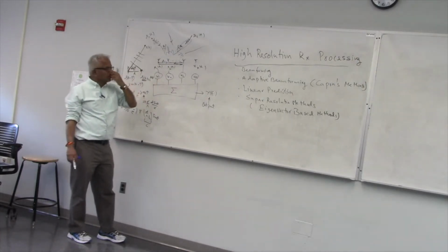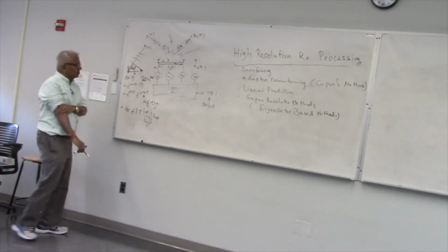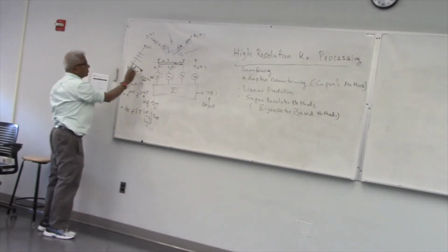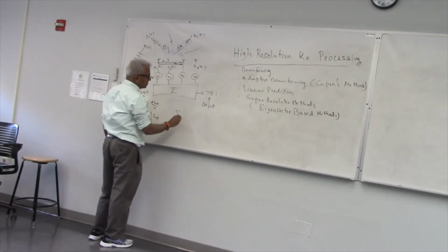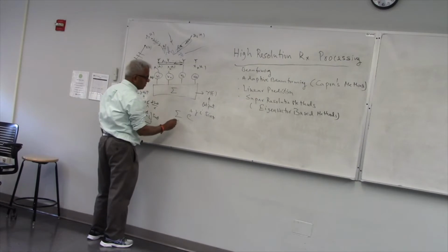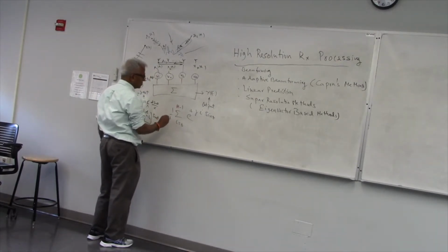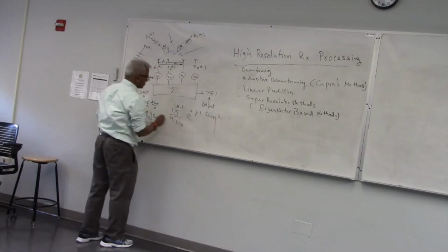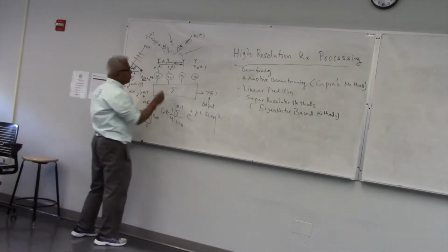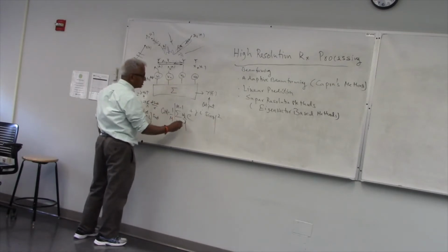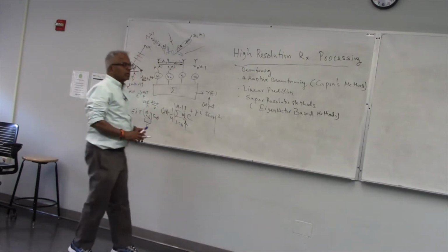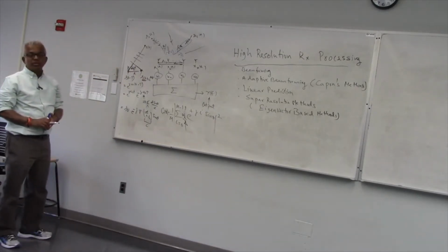How to put here non-uniform weights so that the side lobes are as low as possible. And I went through the general beam pattern for the uniform weight. So a uniform weight would be each of these sensor outputs is shifted and added. So it is going to be e raised to j i sine theta, right? i from 0 through m minus 1, depending on the number of sensors. And you can call this the gain pattern. And we saw its main lobe and peak side lobes we discussed. If you want to put additional weights, this is what you are going to do. You want to insert some weights here. The question is, what are the weights which will suppress the peak side lobes, etc.?